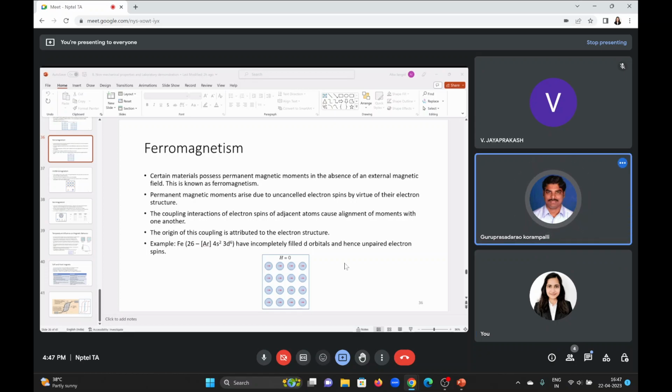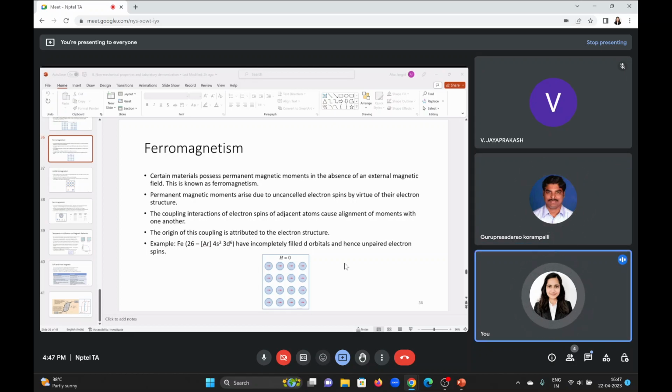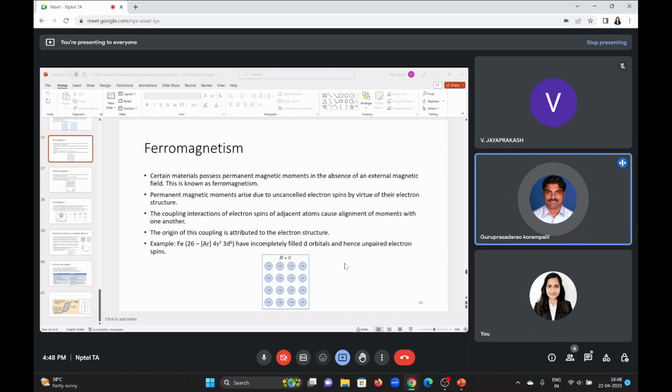Slip system means a combination of direction and plane. Along this direction and plane it will have the highest atomic packing density. So it is easily packed, and it will move easily when you apply some force on it. So it will try to move along this direction and this plane. Okay, thank you, madam. Highest packing density, yes.